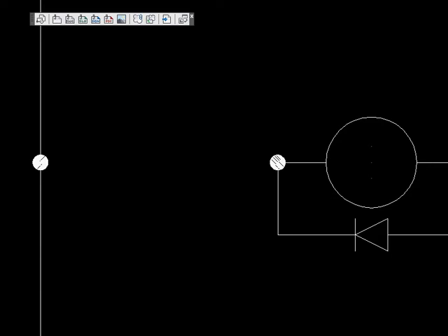So what I've done is I created a block that's got some of these aspects to it. It's going to have a stretch grip, a move grip, and also a visibility grip, where we're able to pick different options of this block. There are going to be 4 different varieties of this limit switch that I'm going to insert. So I've taken my insert toolbar and pulled it down into the user interface here for this video so we can see what we're doing, and reduce some of the clutter associated with some of these toolbars.